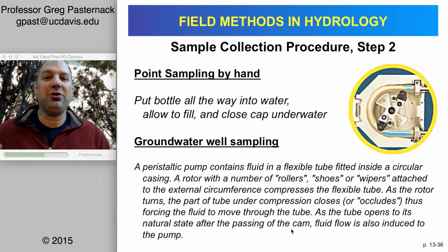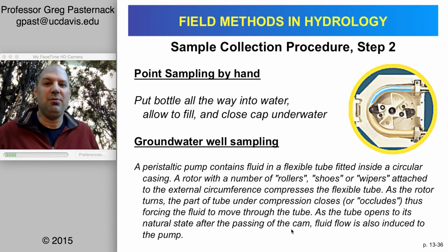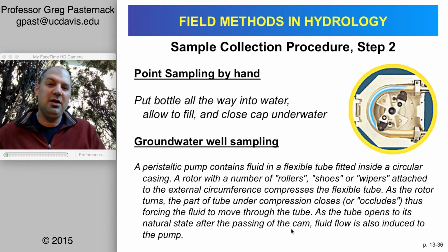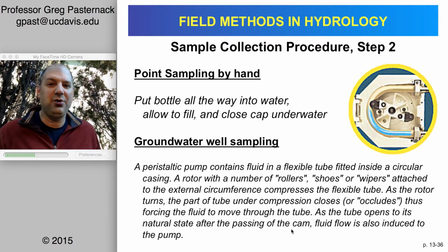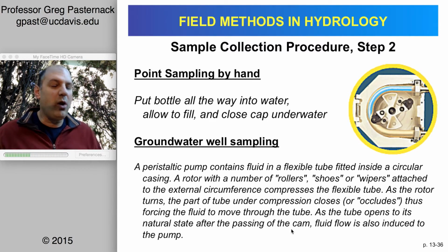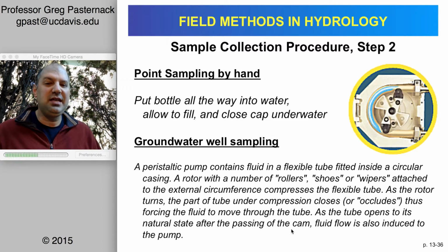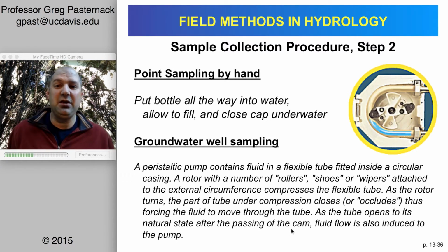Unless the water is literally hazardous to your health, in which case you should probably have gloves and appropriate attire. But if it's safe to put your hands in the water, you're not in the middle of a raging flood or you're going to get swept away or something like that, fully immerse the bottle, close it underwater with no air bubbles in it, so you have a 100% pure sample that's not going to undergo mixing with oxygen in the air.